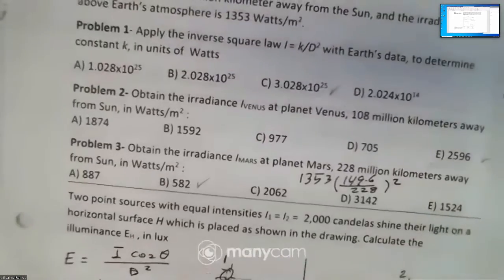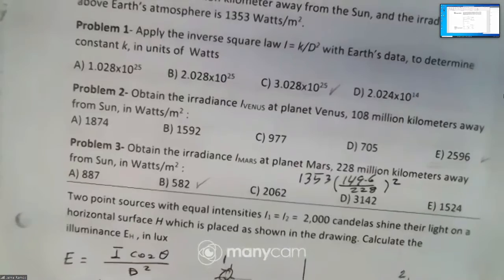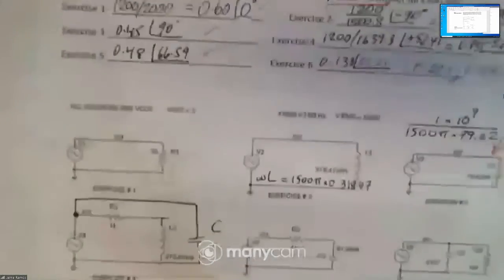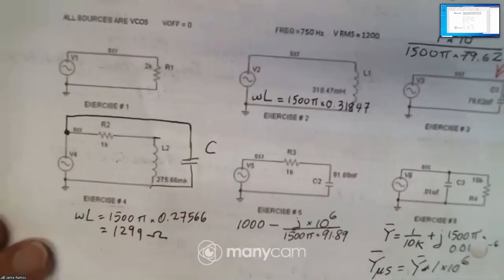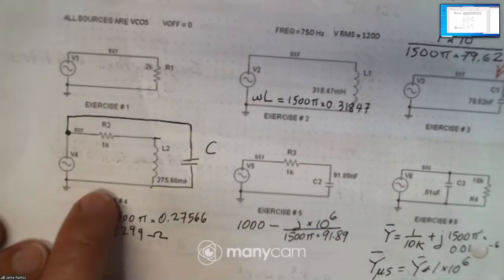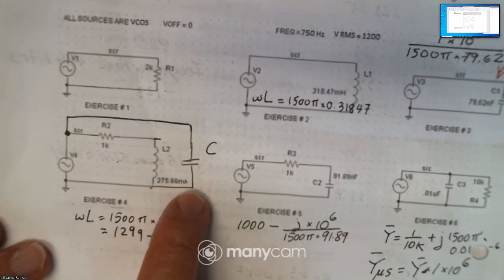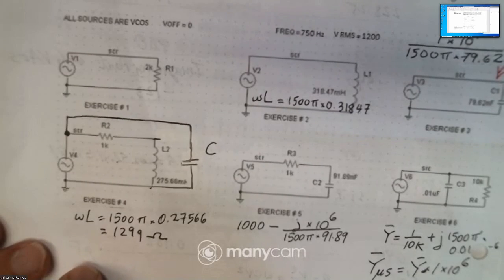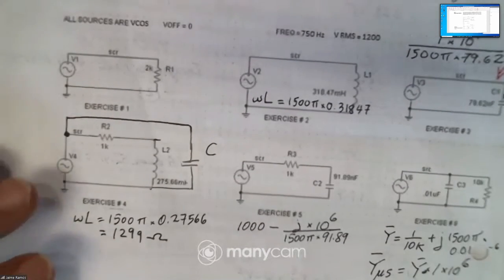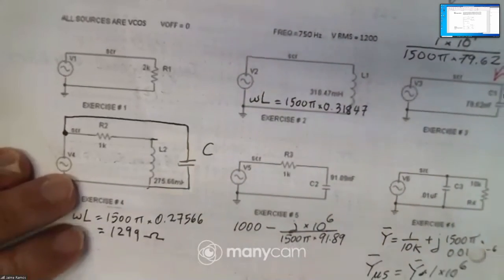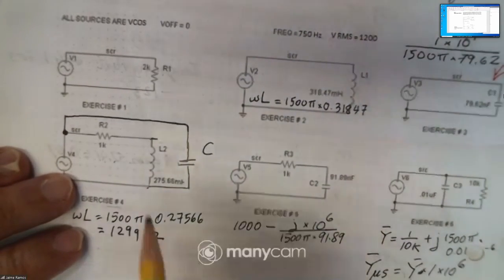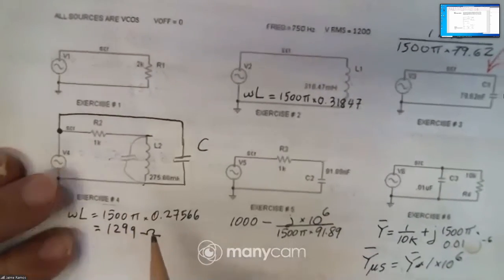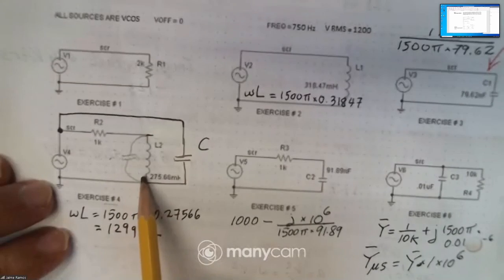All right. One more thing. In homework 1, I made a mistake. So now let me make a correction. In homework 1, remember this problem with the capacitor for power factor correction. The mistake that I made was that I connected the capacitor here directly across the inductance.